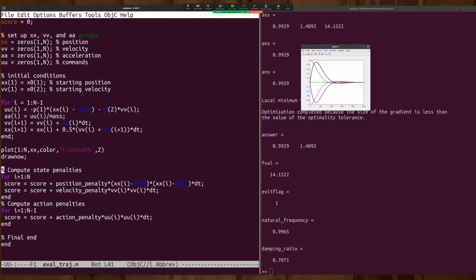And that corresponds to the element on the diagonal of the R matrix. And we're quadratic in the command. So the idea is we run a simulation for a certain length of time, we score it, and the way we optimize the control law is we guess a control law, we run it, we score it. We try something different, we run it, we score it. If the score decreases, that's a better control law. If it increases, that's a worse control